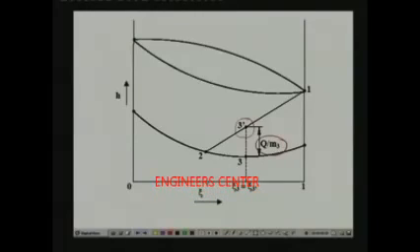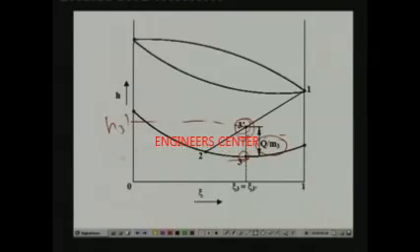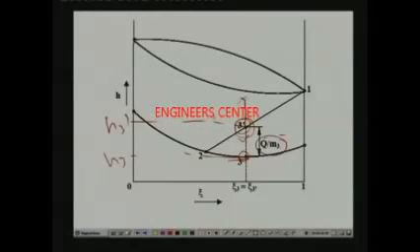So, if you know these two things, first find this point assuming adiabatic mixing, then this point is obtained by drawing a vertical line and going down by this much distance. That means H3 dash is the specific enthalpy without any heat transfer, and H3 is the enthalpy with heat transfer from the system. If the heat transfer is to the system, obviously this point will move up. This is for the positive Q, whereas this is for the negative Q.